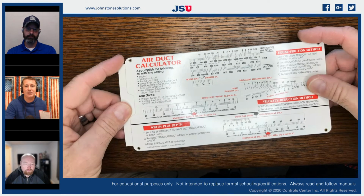So if I take my duct calculator, just for reference, we're going to be looking for approximately 1,000 CFM. So we've got a 2.5 ton air conditioning system, and we want to see what size ductwork we need to run that 1,000 CFM. Well, here's the thing. I can move 1,000 CFM in a variety of different sizes of ductwork, but it's going to affect the static pressure. When we talk about static, we are literally just talking about how much pressure is on that.